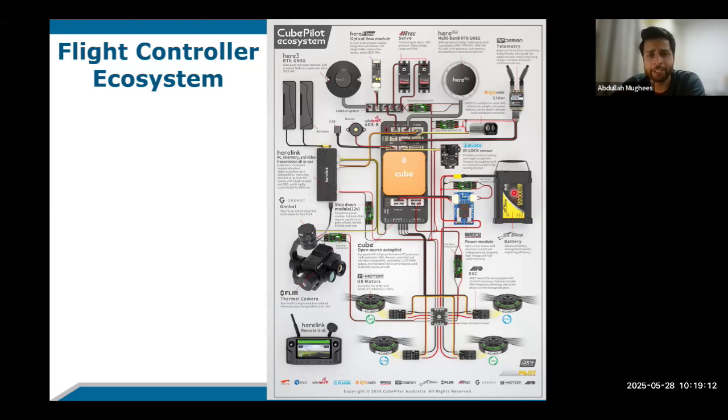And then we have something called an IR sensor, which is not a necessary thing, but it could be used. This is used for nearby obstacle avoidance and distance measurement applications. For example, you could use this sensor for detecting any obstacle nearby for autonomous flights. If your drone was flying and you found a building, a chair or table or anything nearby, this IR sensor would detect, okay, there is something nearby, and gives a signal to the flight controller.